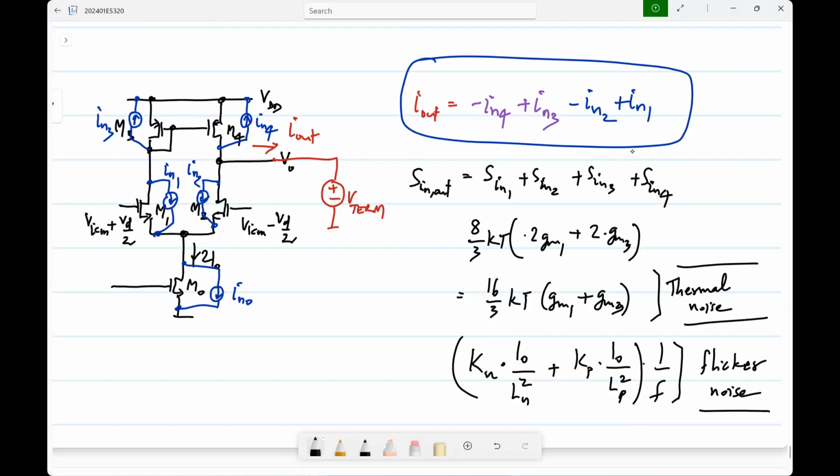Now, for many circuits, and in particular for op-amps, this we also discussed, it is common to refer the noise to the input. Especially for op-amps, because they're always used in feedback loops, this is what usually makes sense. So you can represent the noise of the op-amp. If you look at the data sheets, now you know all these specs, you can go back and look at the data sheets of the op-amps and see what all these are. So you can refer it to the input.